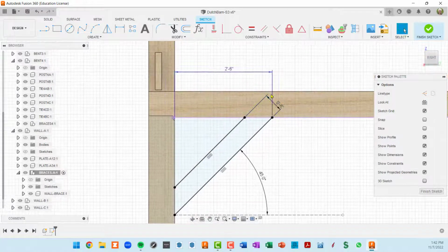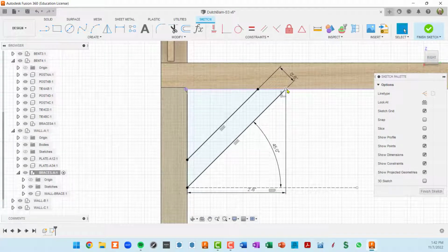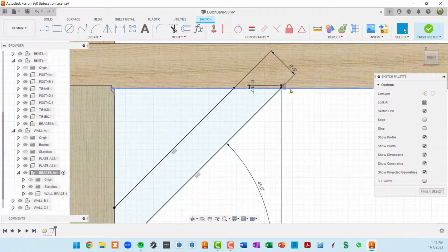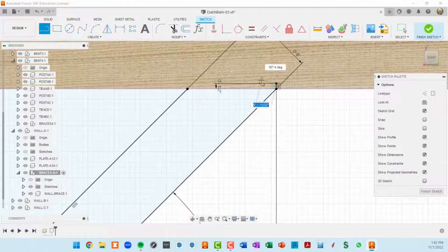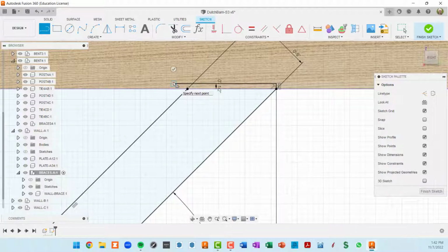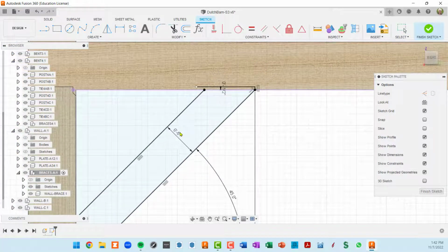So in order to do that, let me clean things up a little bit. I'm going to put my 2'6" dimension down here, and I'm going to press L for line, intersect here, and come up vertical and type in 0.5. So this is going to represent the brace cutting into our beam here. So I'm going to go back to my line tool, and in this case I'm going to keep it horizontal, but I'm going to go too far purposely, and then click. Now if I take this line right here, I'm going to move this down because that's confusing.